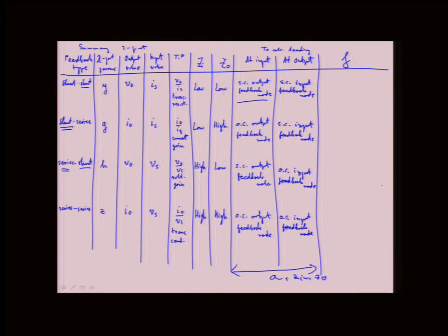We usually, when we isolate the network, will then go and just calculate the quantity from the output to the input. We sort of pretend that the network is unilateral. We can always calculate the other reverse direction too, and then just make sure that the unilateral conditions are satisfied so that we can do those approximations. And we'll touch a little bit on that in the rest of the class.